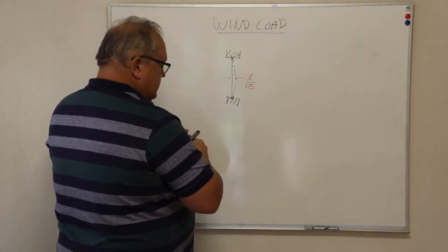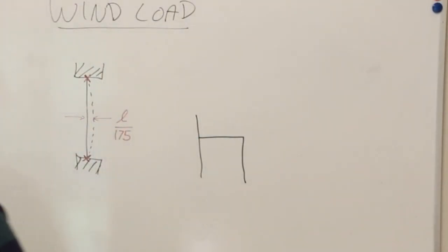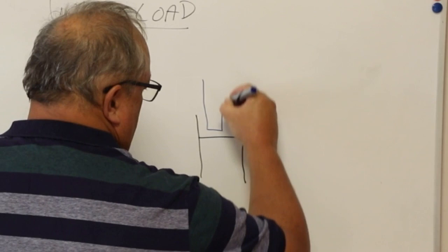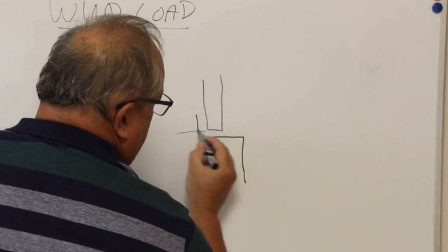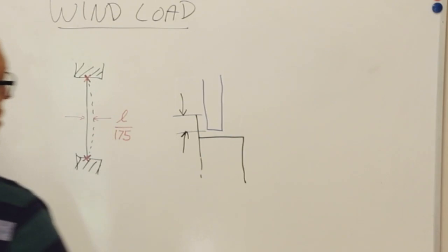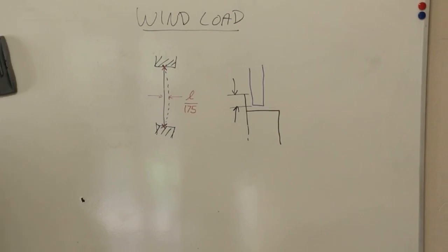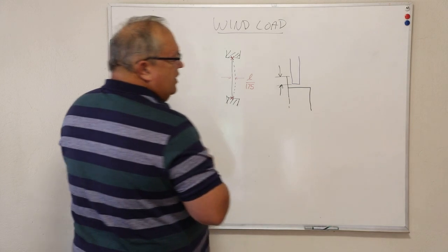If you take a typical outer frame profile, and I'm drawing it simplistically, it would look something like that. I would then have a piece of glass which sits in that position there. Now, when you are designing an aluminium extrusion system, you have to ensure that there is a certain overlap, this distance here, between the edge of the glass and the glazing lip or the upstand. And that is to ensure that that piece of glass cannot come out of the frame.